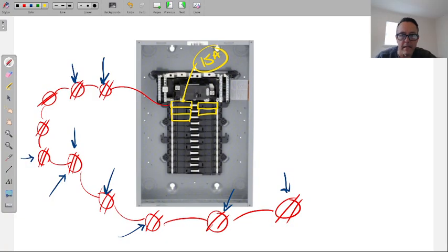And now the electrical company has to come back and take a look at the situation and go, okay, you've plugged in a lot of stuff to your outlets, and you're not going to tell the homeowner, unplug all of this. They're exceeding 15 amps. Let's say they've plugged into all of these outlets and they're somewhere around 25 amps. So definitely your 15 amp breaker is popping. So now what do you have to do?